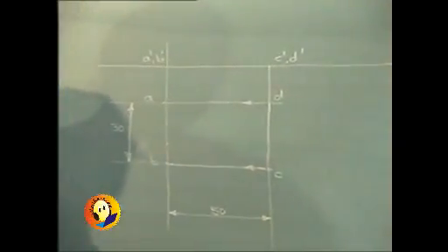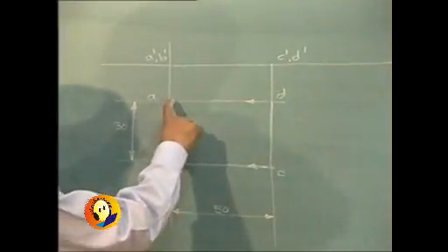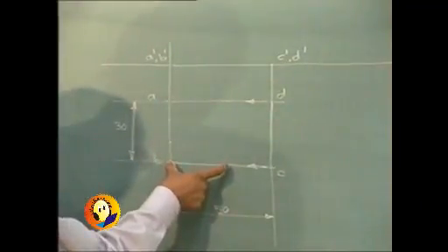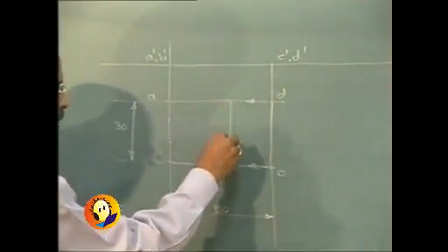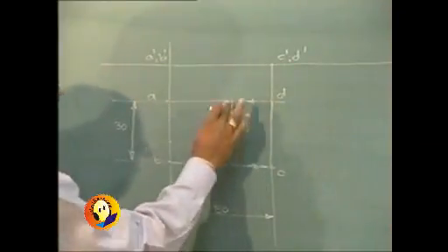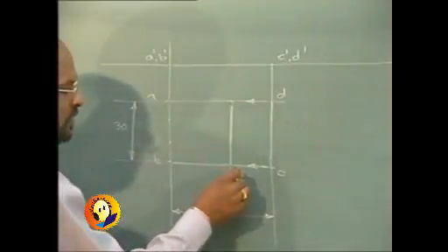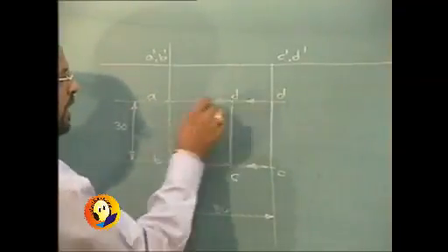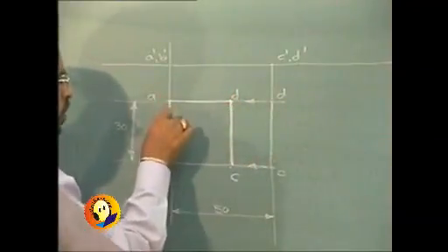When should they stop? So that it will form a square. Now one side is 30, so these two sides should stop at the point where it will appear as a square. So the entire movement will be of 20 millimeters, and this is the final position of point C and D after the rotation, and the top view will be a square.